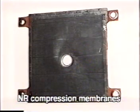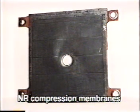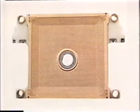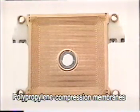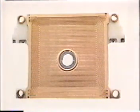The compression membrane for the MF filter press features a unique one-piece structure. No bolts or other hardware are required for installation, ensuring a consistently long life. KURITA makes compression membranes of natural rubber as well as various types of synthetic rubber. Polypropylene compression membranes can be used in fields requiring greater chemical resistance, heat resistance, and oil resistance than rubber membranes provide, greatly expanding the range of applications for compression filter presses.